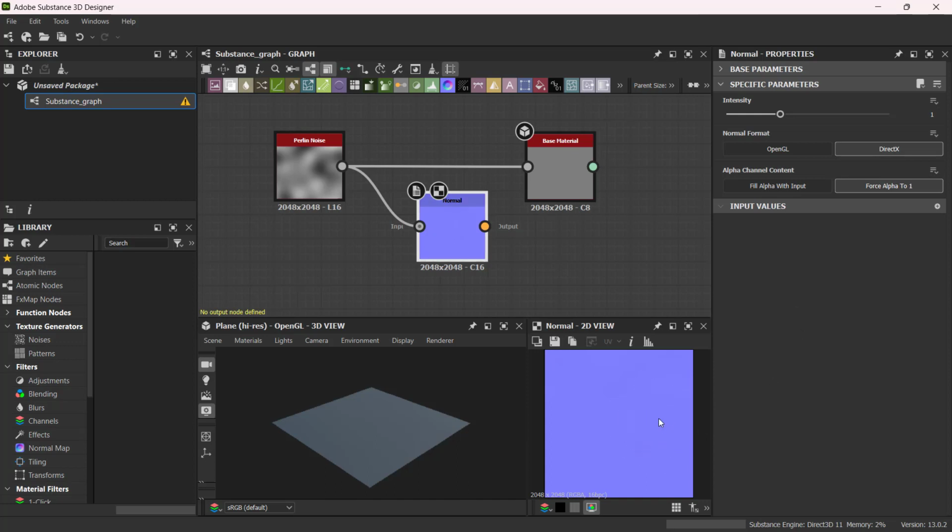So what I will do is go to the normals channel, and I will try to increase the amount, but still nothing is happening because it is just set to 3. I will press undo to adjust the amount. Still in the normals properties, I'll set this, for example, to 20. After I have set that to 20, as you can see, a value appears, or it becomes more obvious. I can adjust the amount further. For example, I'll set that to 30. And from here, as you can see, it's now more visible.